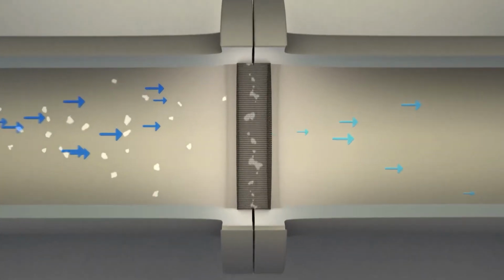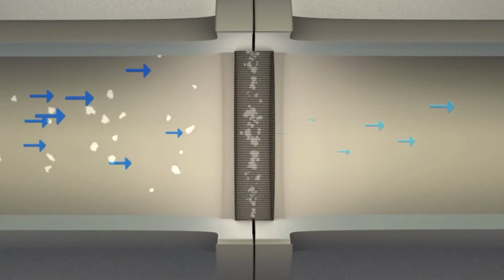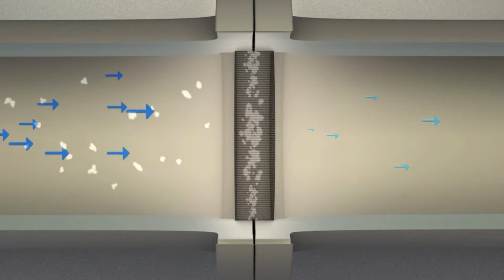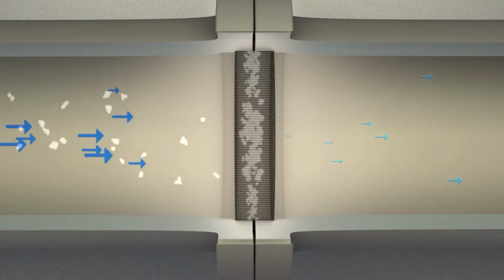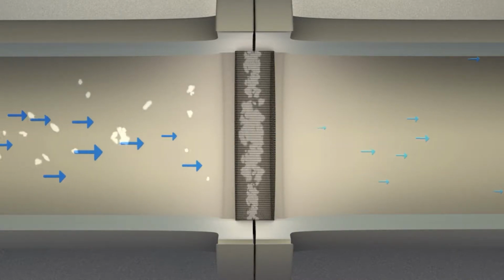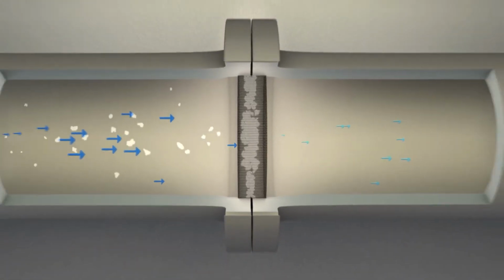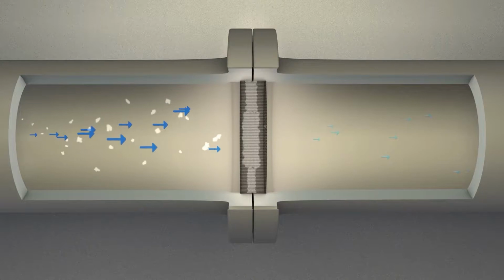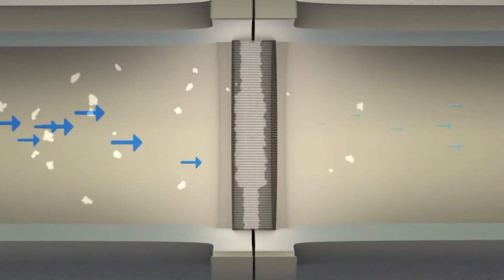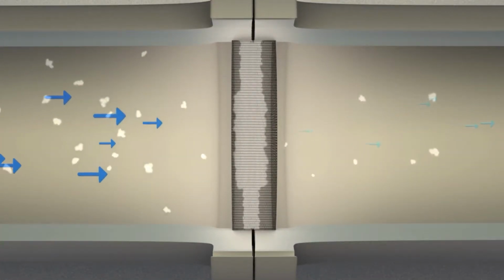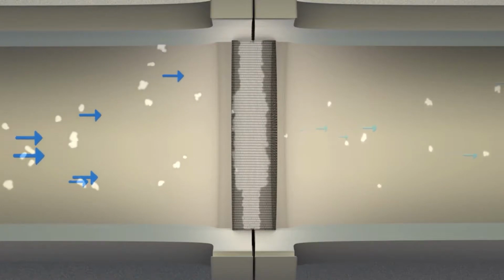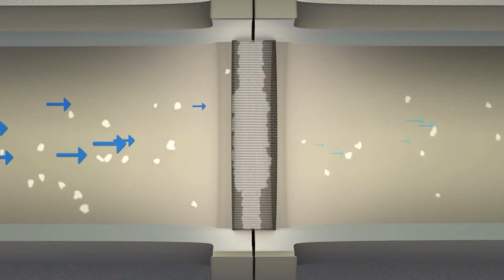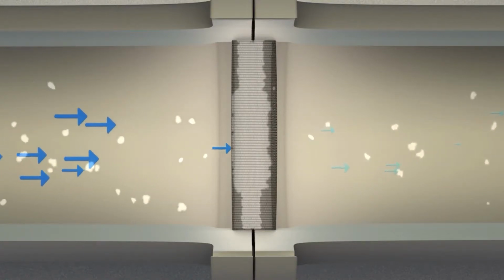Contaminants or particulates that build up in the filter will reduce media flow. As the filter becomes clogged, the downstream pressure drops. This results in an increased differential pressure, also referred to as the delta P or dP. Saturated filters may also begin to shed captured particles. With the filter no longer functioning properly, the contaminants can escape into the process. This is why proper monitoring of pressure drop is crucial.